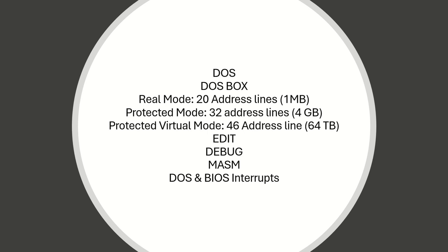So industry doesn't want to shift to a 16-bit external data bus. So Intel released the degraded version of 8086 called 8088, which has the same number of address lines. However, the number of data lines they made 8 externally. Internally it is 16.